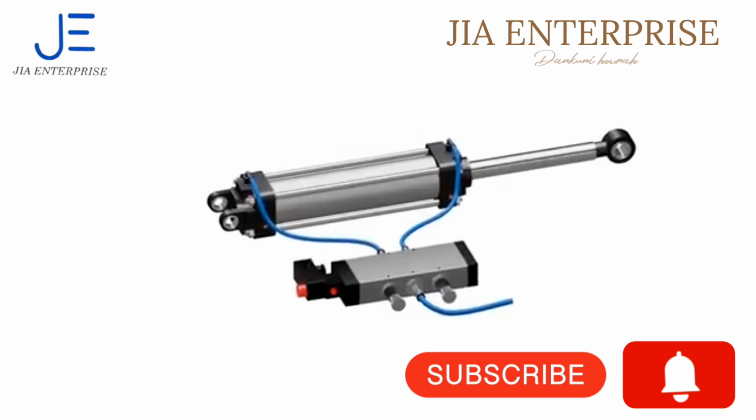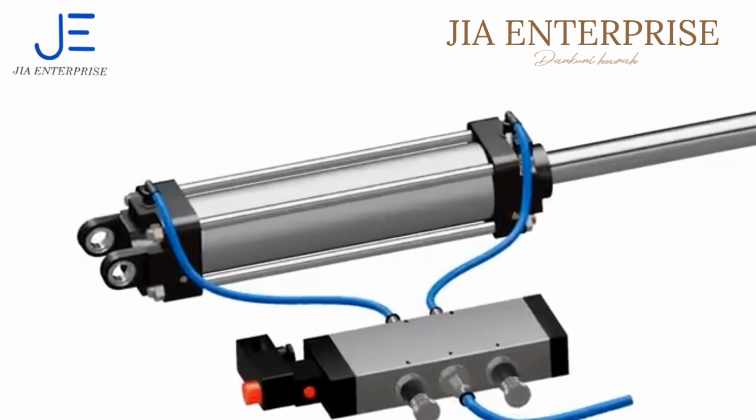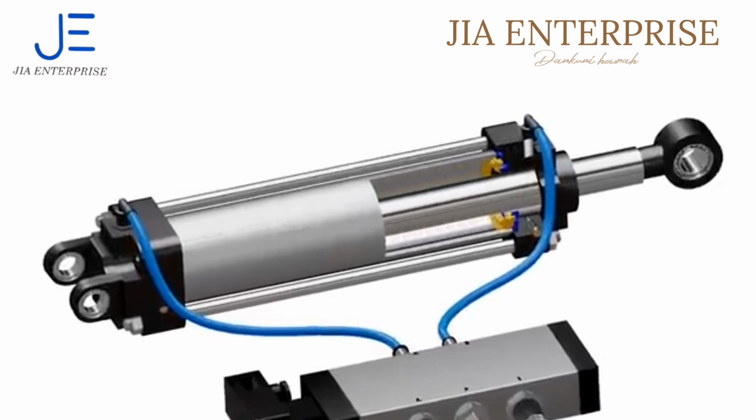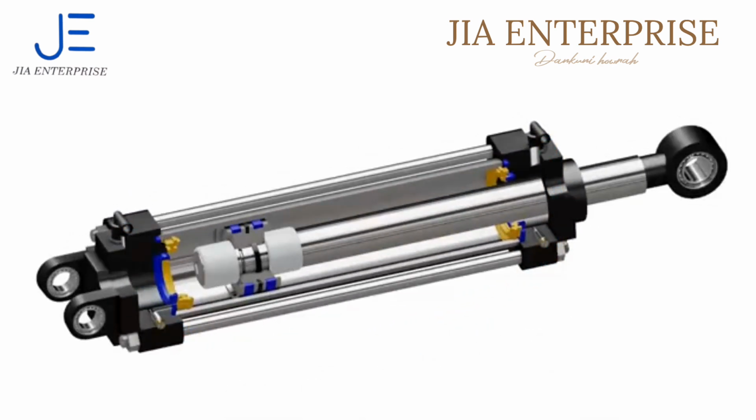A cylinder is a linear actuator powered by compressed air to supply force on a load. The assembly shown here is the most common type of double-acting pneumatic actuator used in industries. It consists of a piston rod. This rod transfers the force of compressed air to the load.